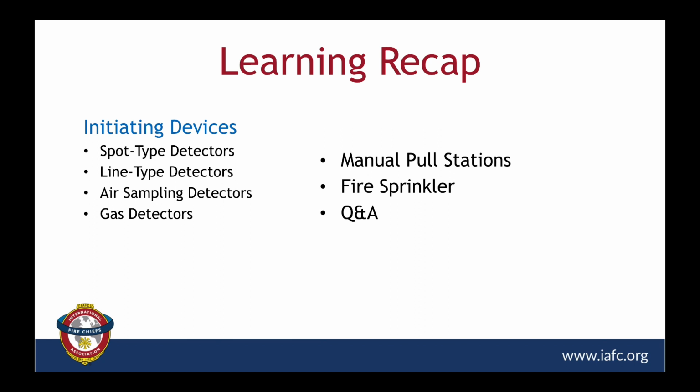One question, or a couple questions, and I'm sure Andy might have one as well. But Richard, one of the things I think that fire departments see, and it varies based on community, but typically national codes are now saying that duct smoke detectors, for the most part, need to be in a supervisory signal. So it doesn't necessarily alert the fire department. When a duct smoke detector is activated, what usually happens in a system?